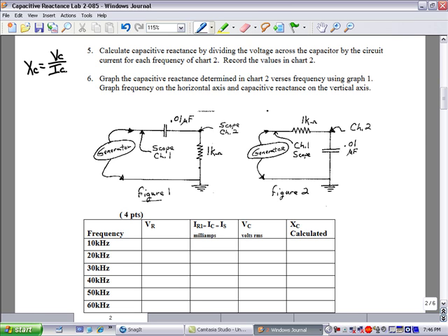You have both because if you have a scope that's connected to ground, you can have some ground loop problems, so you need to switch the components around. You're using a Fluke 123, which does not provide any ground problems, so we can just use figure 1.